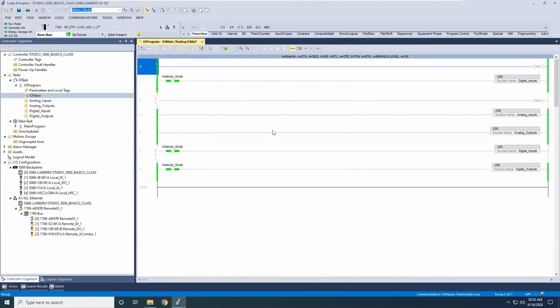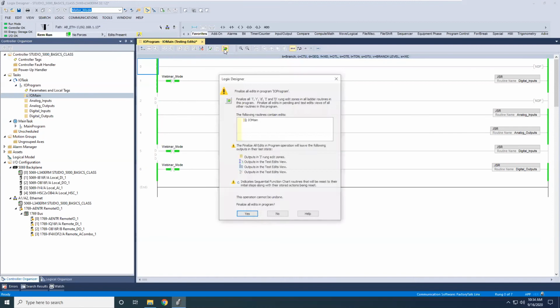So at this point, it will put this into the program, but it's in a hybrid at this point. So you can see that my power flow shifted off of those and up here, but I still have these couple of editors on the side. So I is pending edit and D is deletes. Finalize will store it permanently to memory. If you have a pending, you can untest and cancel and back out and get to what you had. So if you weren't sure that what you were going to do works, you can do this by testing and then, oh, it didn't work, quickly hit the cancel here, as opposed to finalizing, which will download, so to speak, or store these changes inside the controller.